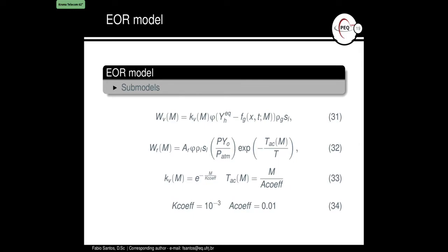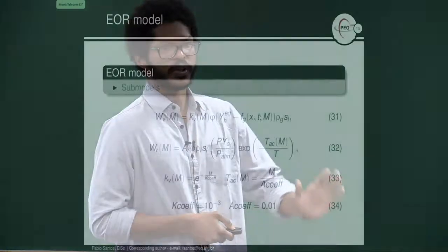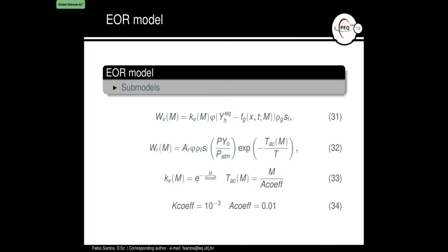The properties and the equations can change during the simulation of the solution based on the moment transportation of the PDF. In this case, we invented these definitions for these source term parameters. We consider that as the molecular weight increases, the vaporization term goes to zero. It's physical, written physically. And the activation energy increases with the molecular weight. And these are the parameters for a test case.